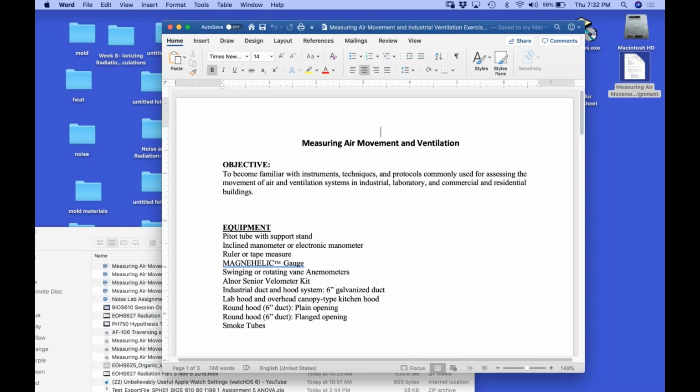So what do we just figure out? What did you just calculate? Q is the cubic feet per minute, the volume of air. So Q is V times A. Okay, so that actually works, right? Now let's take a look at ways of doing other measurements as well.